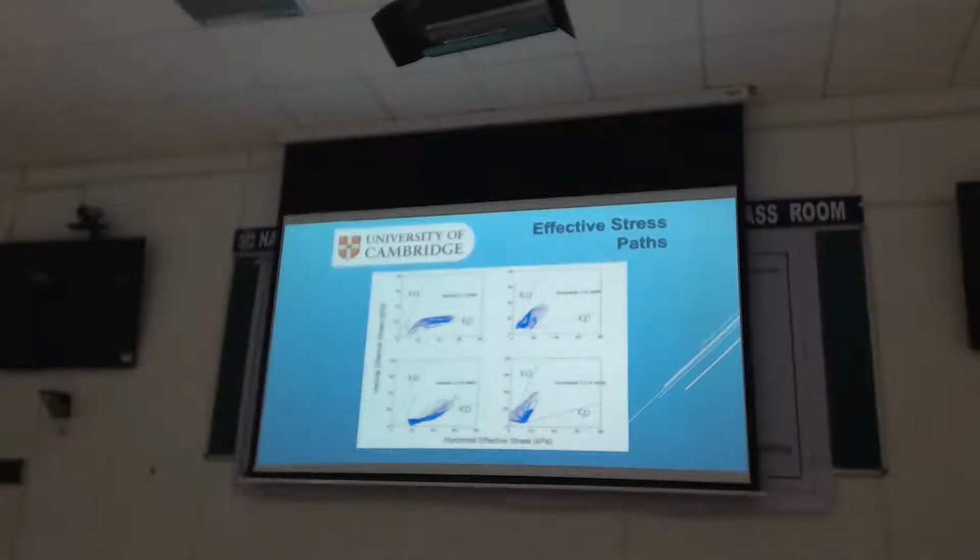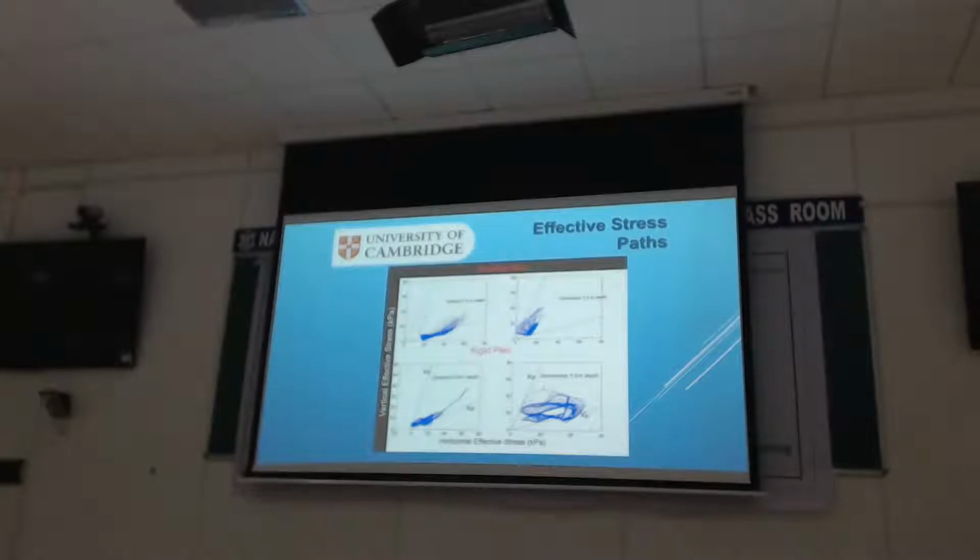So that's the more flexible pile. Rigid piles, less so, in the sense that at the top, clearly Kp, no question, because the pile is not going anywhere and the soil is coming. This one, downslope at the same, oh, I got these labels wrong. That should be 2 meters and this is 3.5.